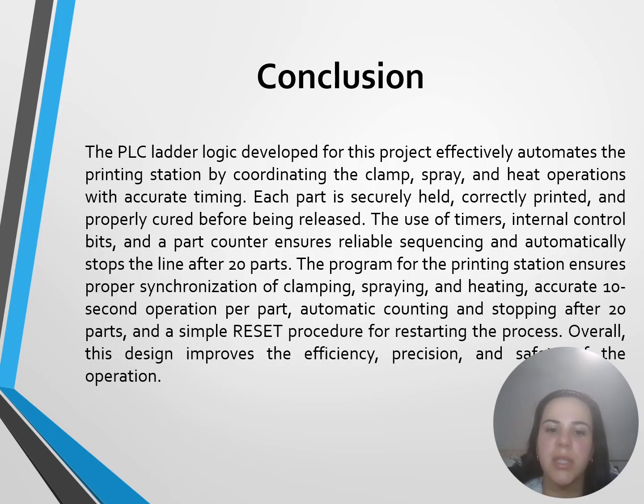The program for the printing station ensures proper synchronization of clamping, spraying, heating, and accurate timing of 10 seconds per part, automatic counting, and stopping after the 20 parts with a simple reset procedure, restarting the process. Overall, the design improves efficiency, precision, and safety of the operation.